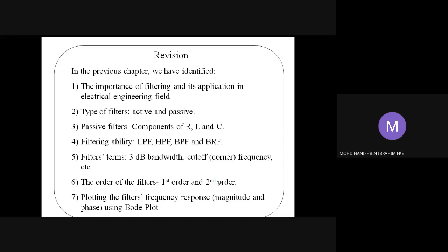We have learned about the circuits of the high pass and low pass filters, which consist of either an RL or RC circuit, because the order of the filter is determined by the number of passive components. You must have at least an inductor or a capacitor in your filter circuit such that you have a first order filter. This is what we have learned in lecture 17.